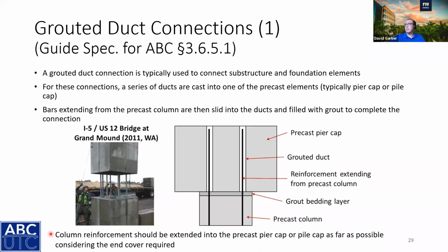All right, so here we have a couple different connections that are mainly for substructure elements. So the first one that I'm showing is the grouted duct connection here. So we have a reinforcement extending from one element and a duct void that's cast into an adjacent element, and then you place the elements together and then backfill with grout.